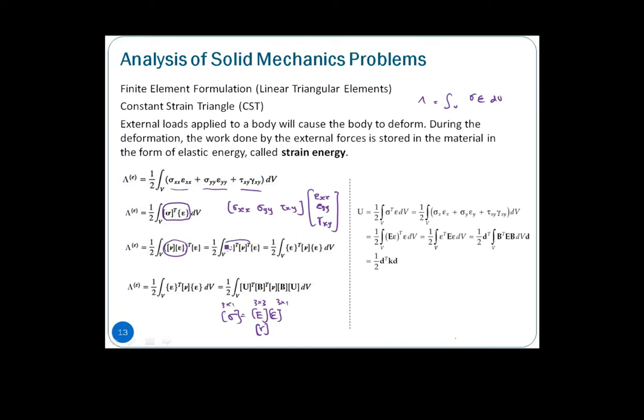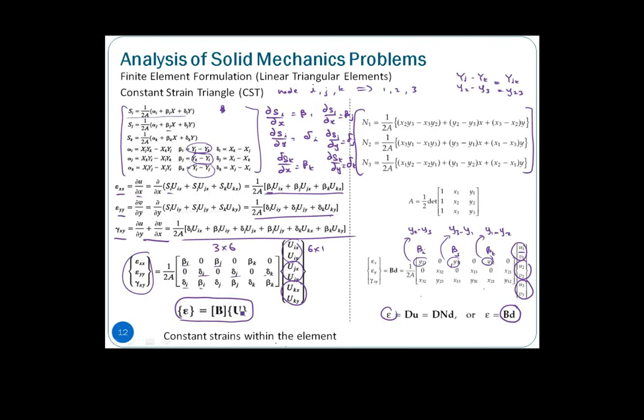So we expand it, and it becomes epsilon transpose, and then E transpose, or nu transpose, okay? So the entire so-called strain energy now becomes this. Then we know that our strain itself, just now, equals BU, which is our strain in terms of displacements.